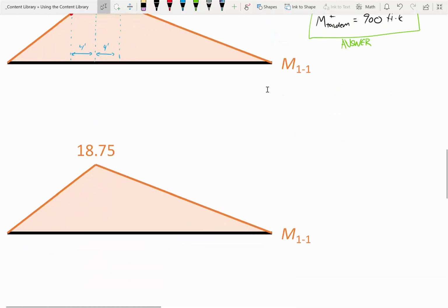Now, for the truck, the way that I find is the easiest to be systematic is I know I'm going to place one of my axles right here over this peak. I know I'm going to do that. Since I'm going to keep my axle spacing at 14 feet, I'm going to lump those loads close together. So I'm just going to split the influence line up into 14 foot intervals, and interpolate the resulting values on the influence line, and let's just see what I get.